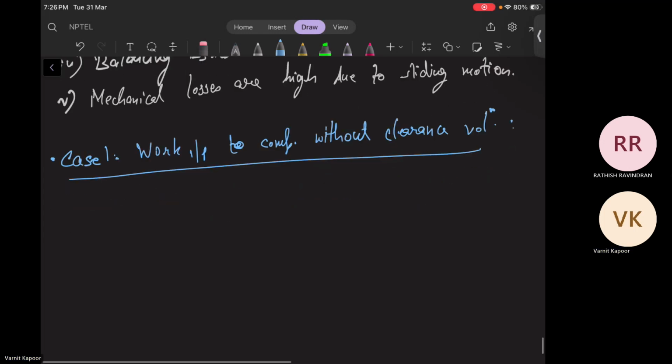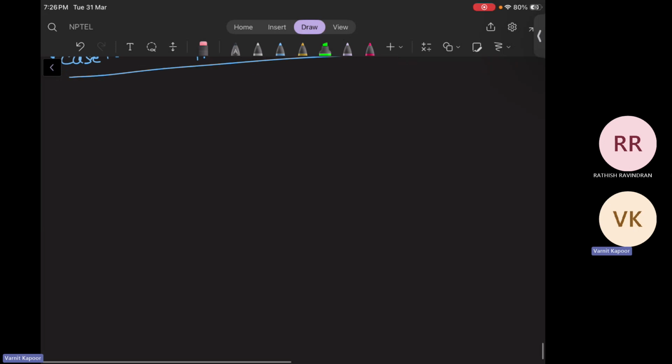Okay. So let us draw the pressure volume plot. For getting the work, we need to see what the pressure volume plot is. And it's an open system device. Compressor has both energy as well as mass interaction taking place. For an open system device, you plot the area under the graph on the pressure axis. So let us make the pressure and volume axes. Initially you had a pressure of P1, lower pressure.